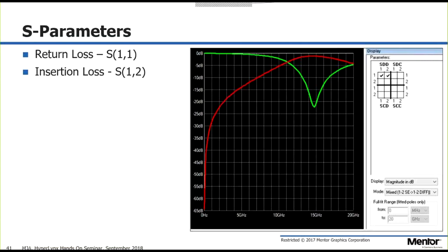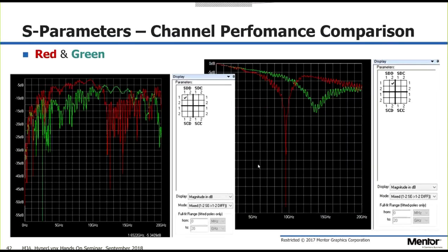So if I had a via built like this and I was going to be using it at, say, 5 gigahertz, I'd say that's probably pretty good. At 5 gigahertz, we don't have a problem. But if this particular via was something I was planning to use at 15 gigahertz, I'd want to go look at a different via pattern. That's not going to be good for that via. I mean, most of the energy is just going to get reflected back. So with that information, let's move on to some more complex S parameters.